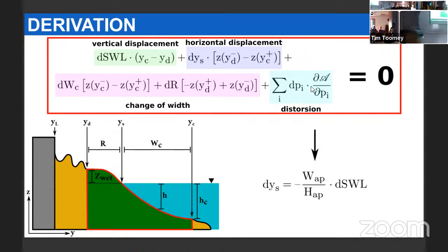Absolutely. So we were discussing that, for example, the characteristic sediment size makes the slope of the profile different. Also there are distributions of the different materials. Also, depending on the shape or the characteristic of the material, the slope is different because it's not only the size of the sediment, but also its settling velocity.